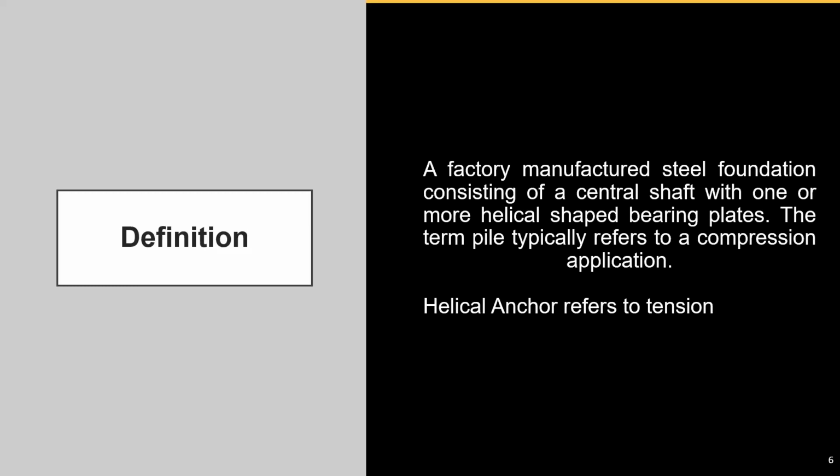And the reason why, because most of this data that we've been collecting for the last 30, 40, 50 years, is based on small diameter shafts. Now, large diameter shafts, they are there and they use them also, but we don't have enough data to really, for instance, say what is the KT value for that shaft size, such as 6.5 or 8.5 inch outside diameter shaft. We don't. We don't have enough data to say what the KT value is for that shaft size.